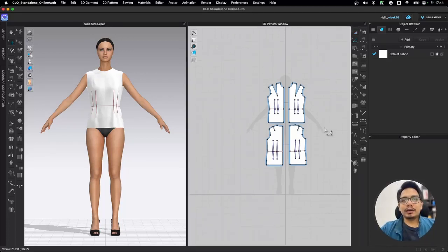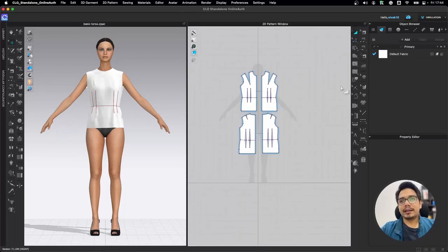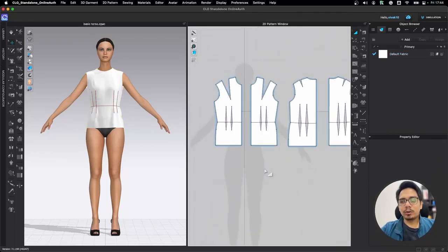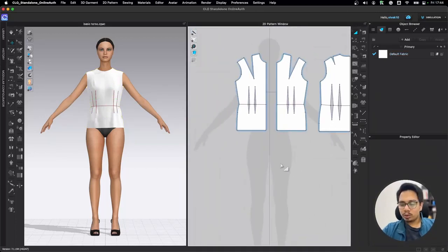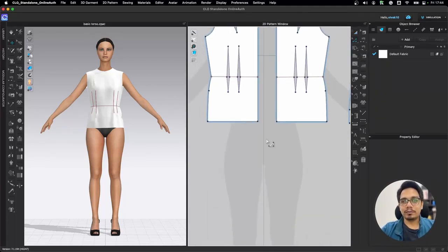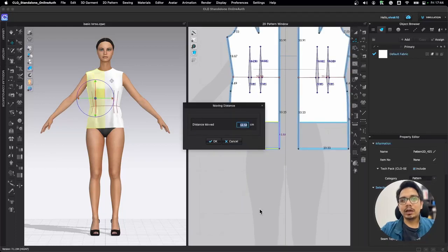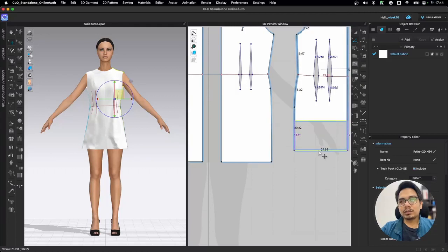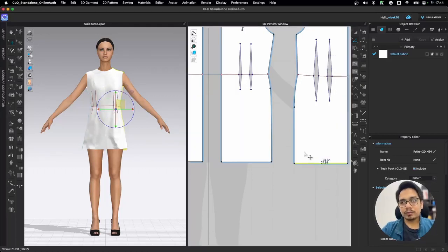When I say modeling, what you need to take care about, as I said, is that we have to be technically a little bit correct. I'm not going to go into tutorial mode, I'm just quickly doing it, but whenever you are editing anything, you have to be precise. So maybe we want to move this, and this value right now is in centimeters. So maybe let's do 20 centimeters. And in the same way, we are going to move this also by 20 centimeters.